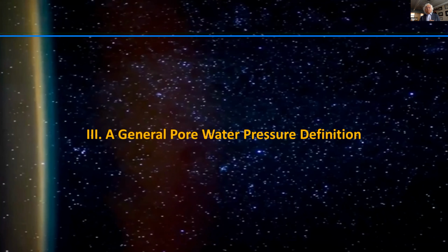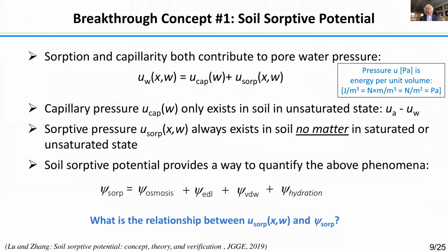So to define the water pressure in a sense that we can include all those mechanisms, we can define the pressure in soil into two components. One is due to the capillary, which simply follows the mechanism. The other one is due to absorption. The capillary one is a mechanical interaction of the surface tension with the soil and with the water. So it's an energy directly through mechanical energy. However, the one that we call absorption pressure, that I alluded to, is due to the summation of these four different electromagnetic waves provided by the soil due to the absorption.